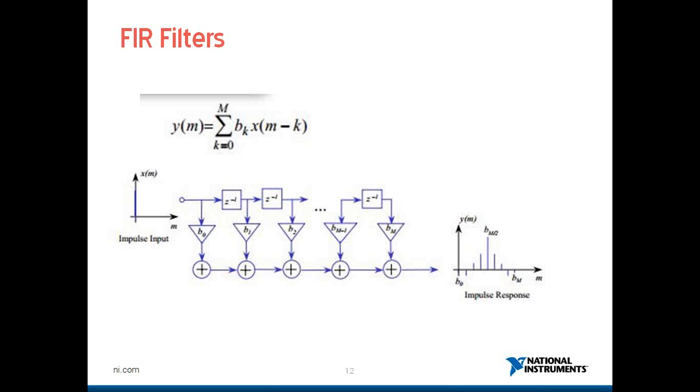Now generally we prefer to use FIR filters when you have applications that want linearity in the phase. So when the application demands linearity in phase, you would want to go with an FIR filter. However, if you had a requirement where you want to extrapolate on the traditional analog filters, then what you would like to choose would be an IIR filter.